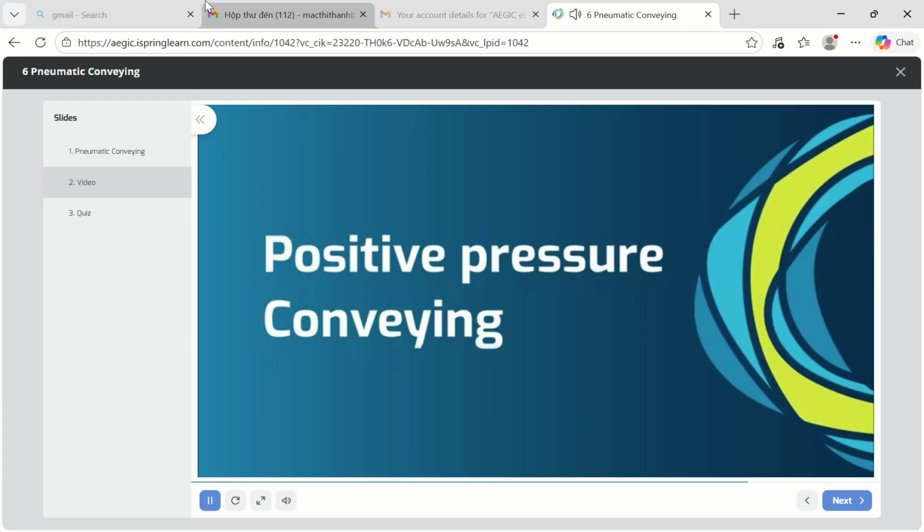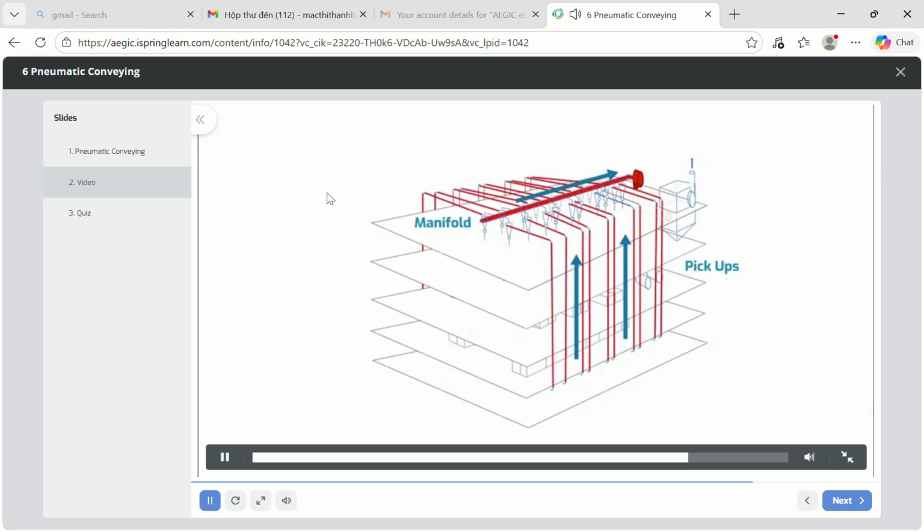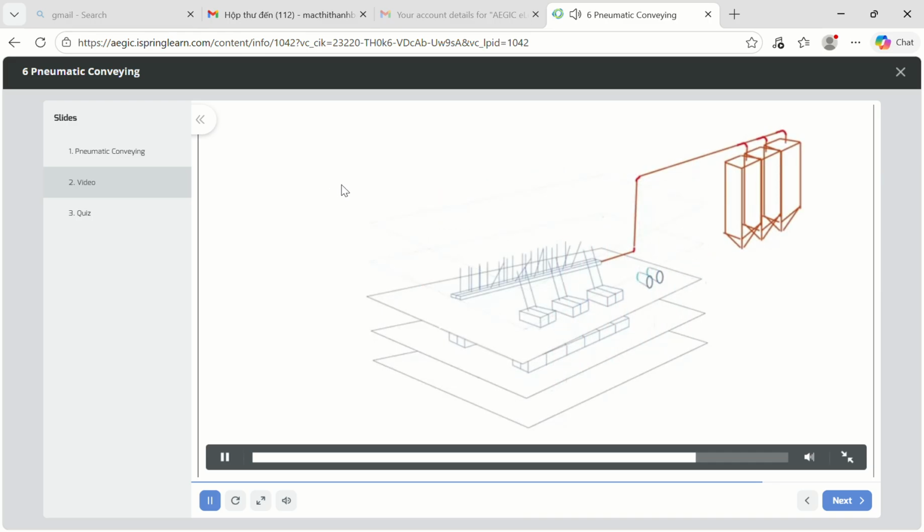Positive pressure pneumatic conveying. Unlike negative pressure systems, which tend to collect air streams from multiple points, positive pressure systems tend to convey stock from a single point to another single point, or perhaps a few possible points, but only one point at a time. For example, a positive pressure system can convey flour from a collection conveyor to one flour bin within a nest of possible flour bins.